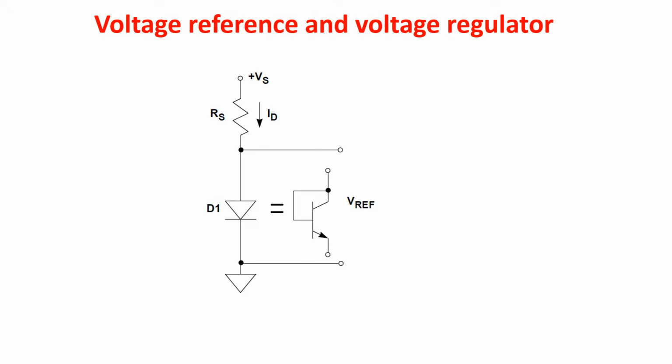Reference circuits and linear regulators actually have much in common. In fact, the latter could be functionally described as a reference circuit but with greater current or power output. Voltage references have a major impact on the performance and accuracy of analog systems. Accuracy of the voltage reference is important, as well as temperature drift and noise.